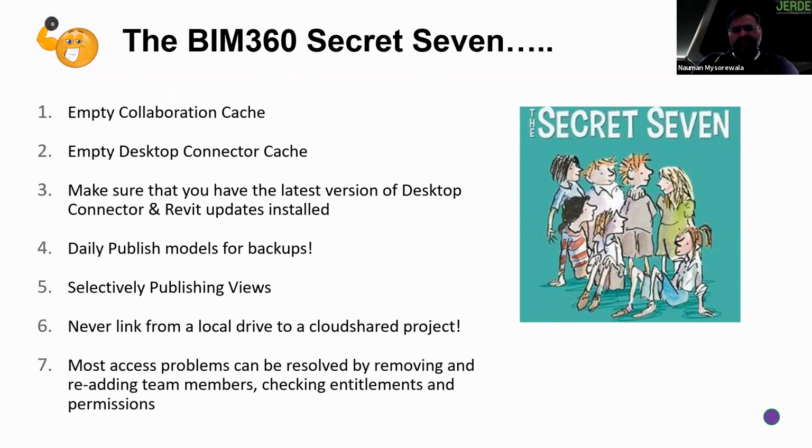And most of the problems accessing and removing, issues with can't edit the file. Sometimes you can't open the file from BIM360 or it's grayed out. A lot of times it can be that you should make sure the licensing is correct between the users. Make sure that you add and remove the team member as well, making sure that you have assigned them the correct permissions, whether they have access to BIM360 docs or you have the design collaboration access model. So you will have to make sure that all those items are there and that you've set up the teams correctly as well.